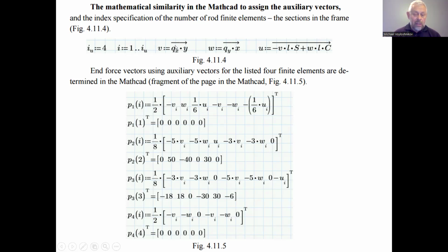Why do we do that? We do that so as to consider in the next the v magnitudes as the elements of a vector. So this is v with the index y. The variable y means that this is an element of the vector v. But to do that, first we have to assign v the definite function and the concept of the vectorization. That is why v is a vector in the Mathcad computer algebra system.